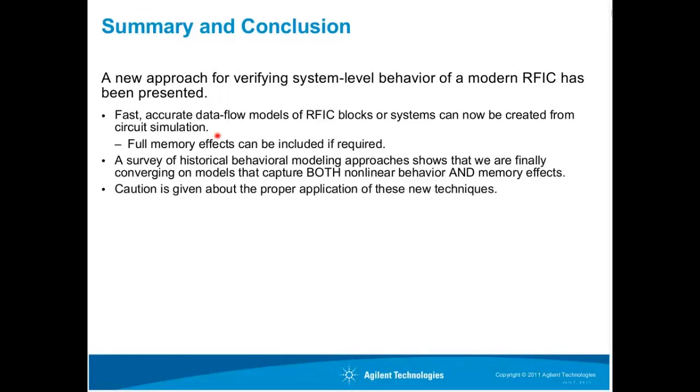I've cautioned you about sharing models. Especially for the GoldenGate users out there, if you've used fast envelope in the past to speed up your simulation, don't think that producing an FCE model is the same as running fast circuit envelope. It takes quite a bit more forethought and planning. You can produce a very good quality model for use within SystemVue, but you do have to know more about your circuit and about the application in SystemVue before you produce that model.